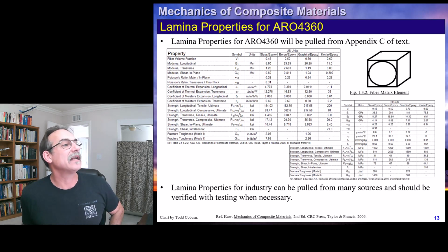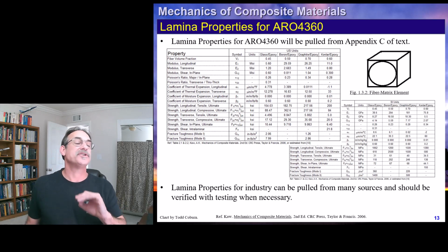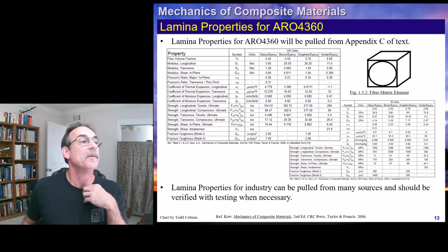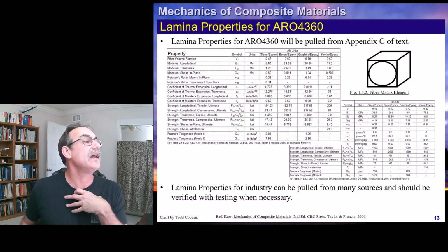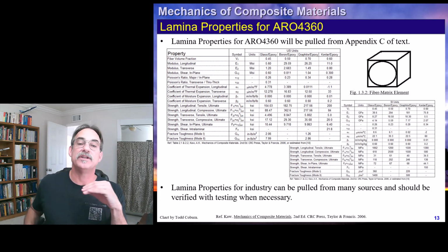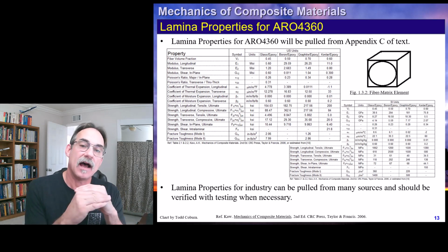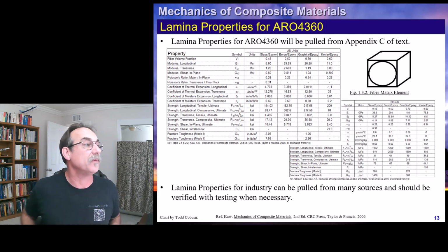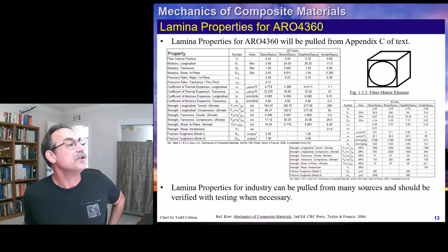If we go back to glass, we see our longitudinal modulus in the strong direction is 5.6 million psi, and in the transverse it's 1.2. Transverse being the widthwise direction, but we can use that actually for both width and thickness if we need a value. The shear in-plane modulus is 0.6 MSI, and so on.